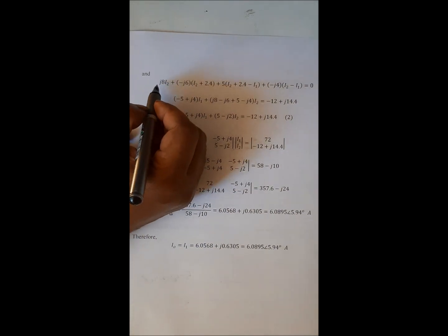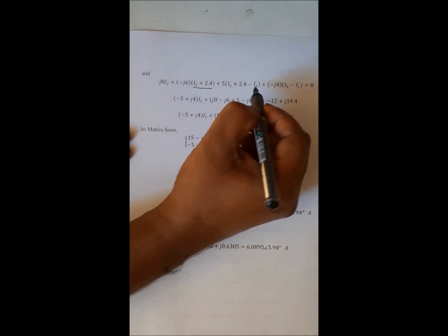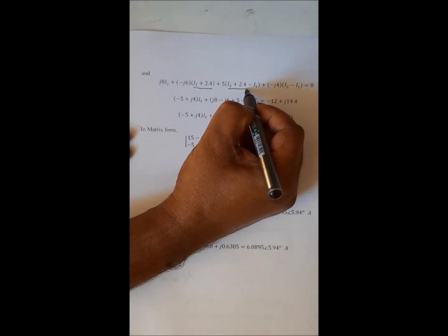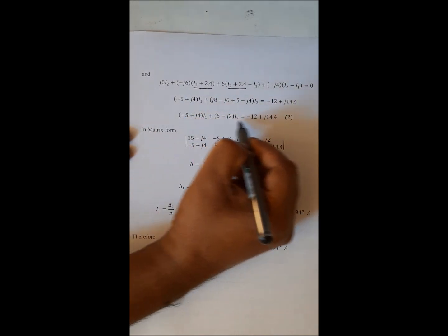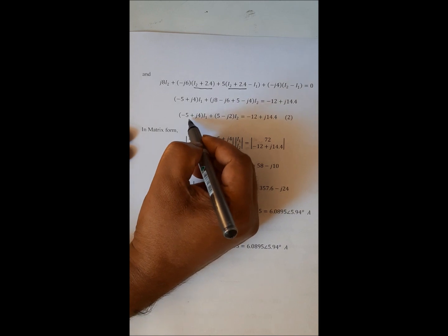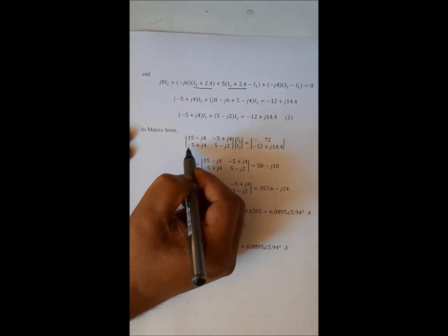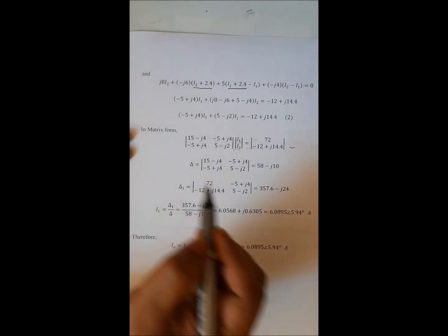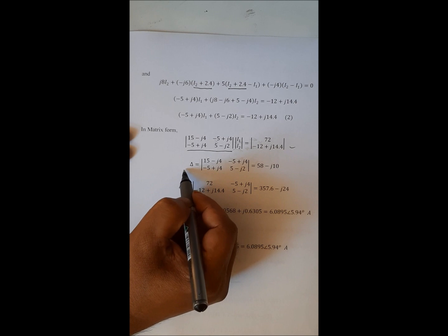Now we can find the equation for the super mesh. For the super mesh, if you substitute I3 with I2 plus 2.4, then we simplify this equation and eventually come up with this. So for equations 1 and 2, we put them in matrix form and we build this matrix. After finding this matrix, we find the